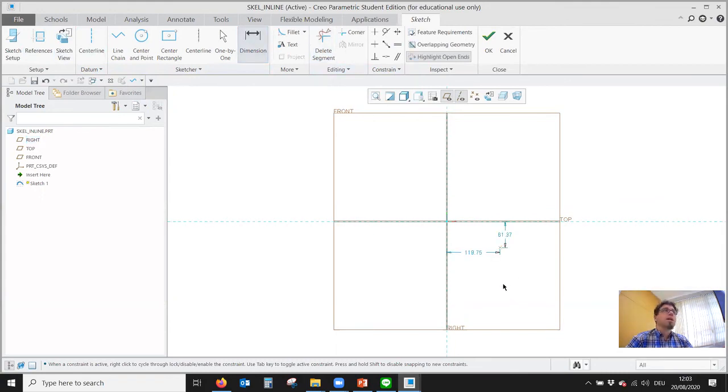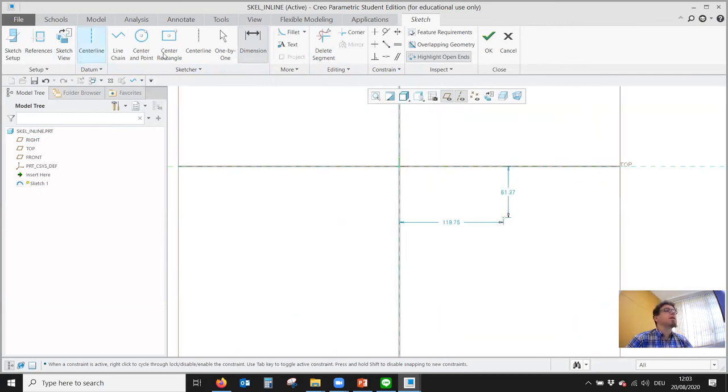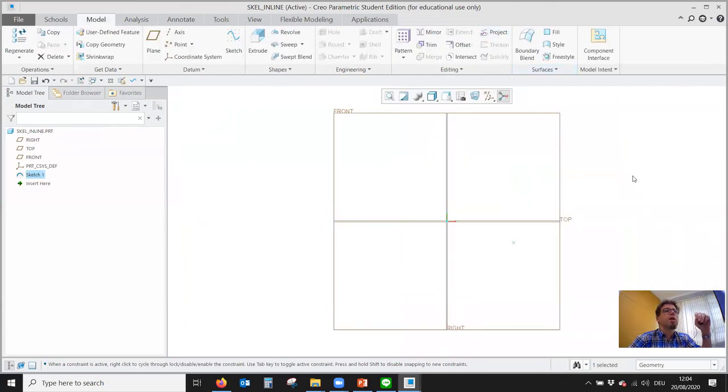Now what is important is that you're using dimensions to create that point, because later I want to use these dimensions as patterns, right? So I'll just say, how many wheels do I have? 4. So I have 3 distances, maybe 100. So that would be 150, 150 here and 50 here, maybe. So with these 50, I'm defining the distance to the shoe.